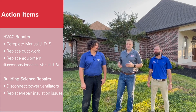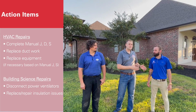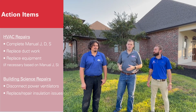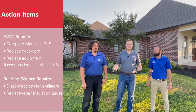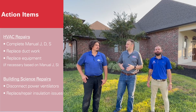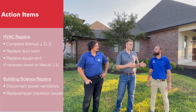Now, that doesn't solve all problems, but we identified that Cody could make a solid decision by pulling in a building scientist, and our building scientist here, Dustin, then ran a blower door to confirm that the shell was not super bad, right? It's average, it's controllable. We're not going to guarantee 50% humidity in this house every day of the year, but we're probably not growing mold or mildew or having issues like that unless they're coming from something else.